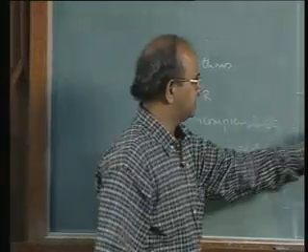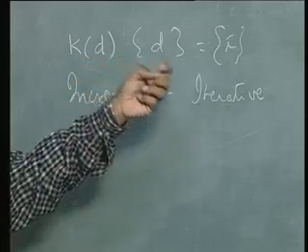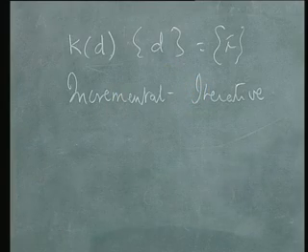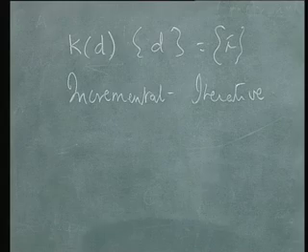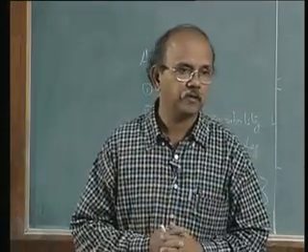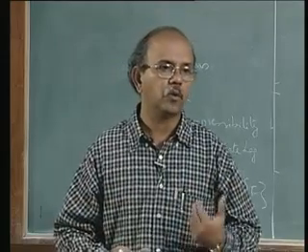What it simply says is that since k is a function of d, I can't apply all the force straight away. I have to apply the force in an incremental fashion. That means that if I am given 1000 newtons, I don't apply all the 1000 newtons at one go.